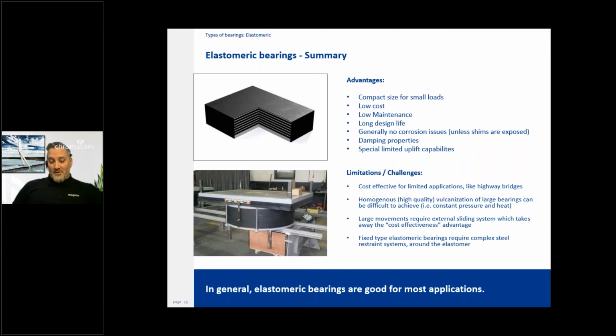They have damping properties, which, like I said, is not common to any of the other bearing types. They resist the load while simultaneously taking a movement. So this can be a favorable attribute. And then there are instances where uplift is possible in a simpler fashion than some other designs.